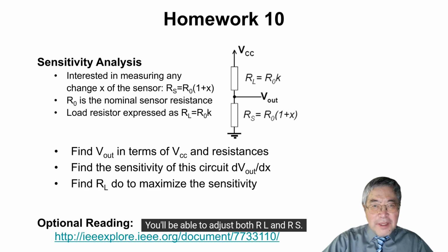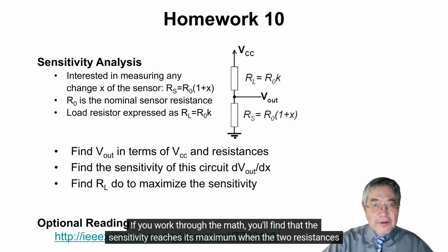You'll be able to adjust both RL and RS. If you work through the math, you'll find that the sensitivity reaches its maximum when the two resistances are equal.